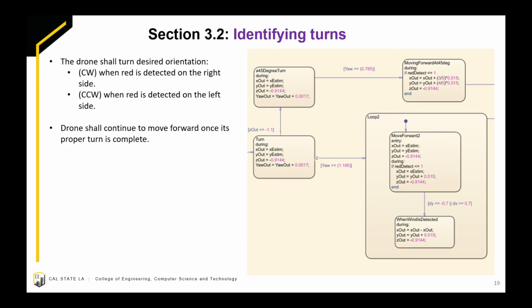Depending on where the drone finds its new red path, the drone will either make a plus or minus 90-degree turn or a 45-degree turn, and then moves on forward until the end of the path is reached. The next block tells the drone to stop and maintain its hovering position at 3 feet.